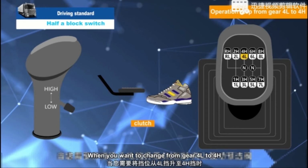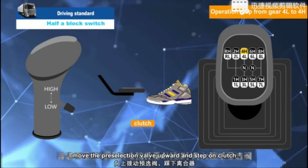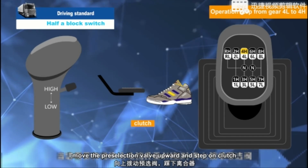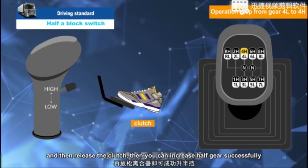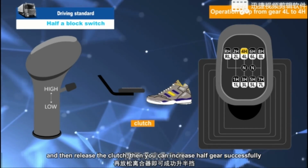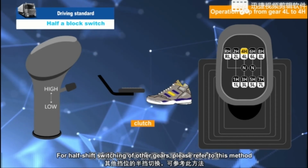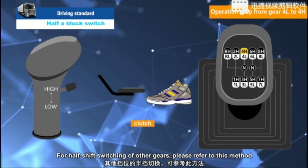When you want to change from gear 4L to 4H, move the pre-selection valve upward and step on the clutch, and then release the clutch. Then you can increase half gear successfully. For half shift switching of other gears, please refer to this method.